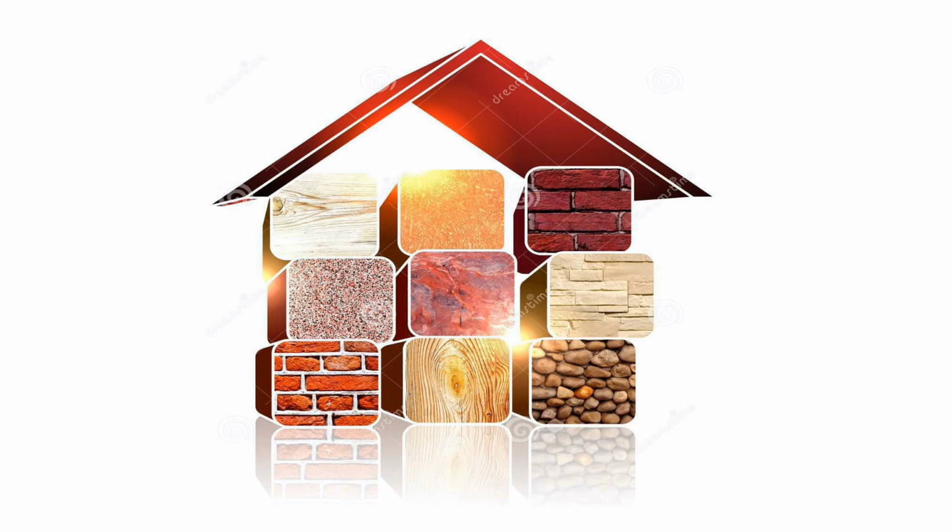With drying any building, residential or commercial, you cannot dry what you don't know what you're drying. You've got to find out what the material is. Sometimes that means a little bit of destructive testing. Sometimes that means drilling a hole in a baseboard and getting a sample of what you're doing. But be sure, after you get your asbestos test, that if you have to drill a hole into something, you find out what you're drying.